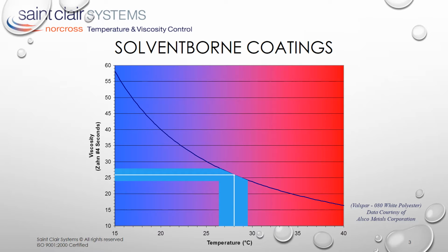should be okay. In a system without temperature control, little can be done when the paint is above 29.5 degrees, and the resulting viscosity is below the lower 24-second limit. Other parameters, pressure, speed, flow, etc., must be adjusted to compensate. More often, however, the coating temperature is below 26.5 degrees centigrade, and the resulting viscosity is above the 28-second upper limit. The most common practice in this instance is to add solvent to reduce its viscosity.